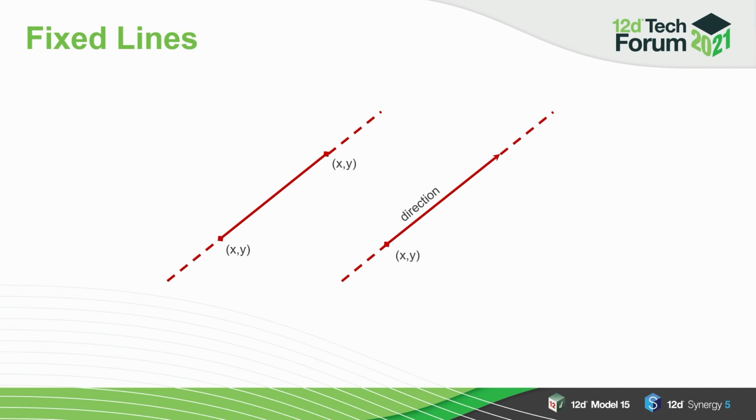The first element part in our arsenal is the fixed line. This element part is used to define straight lengths of road, whether that's horizontal or vertical. In this PowerPoint, I'll just talk about horizontal geometry, so I can be clear, but the principle is the same for vertical geometry. So to define a straight length of road, we need two pieces of information. Either two X and Y locations, or one X and Y location and a direction.